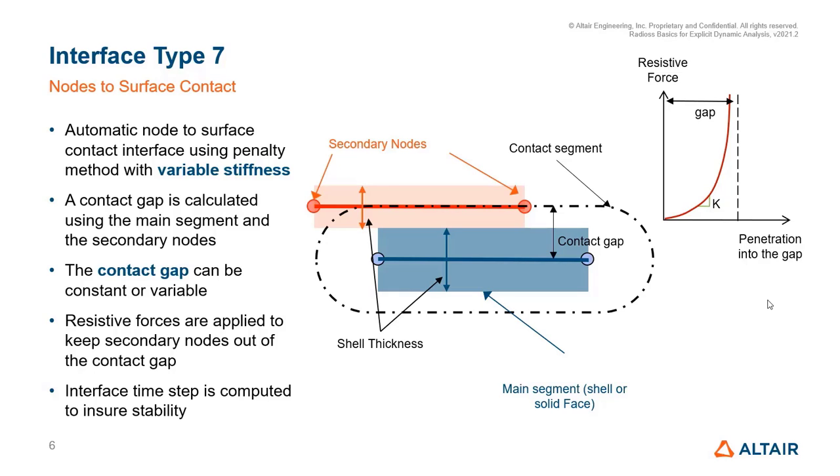So since it is non-linear stiffness contact, it will be governing, or it will control the time step. So in order to stabilize the simulation along with the nodal time step, you can introduce interface time step.